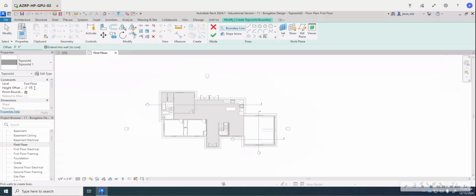And here we've got a depth of -2 feet. That is where you would want the ground to be below your first floor. The ground or the grade level of the property should always be lower than the height of your front door, to prevent water or snow runoff water from actually entering the house. So if you have 0 here, what you would do is you would highlight that and put in -2 feet.